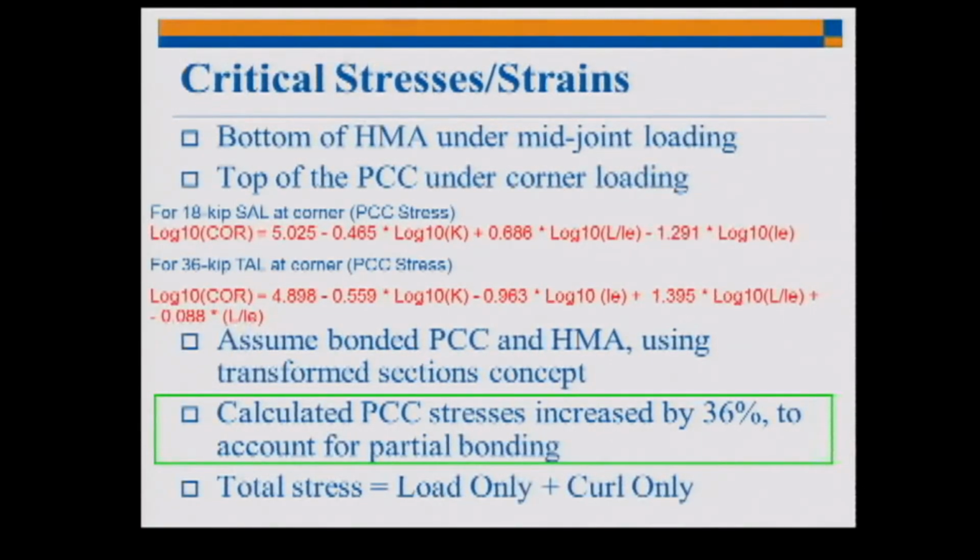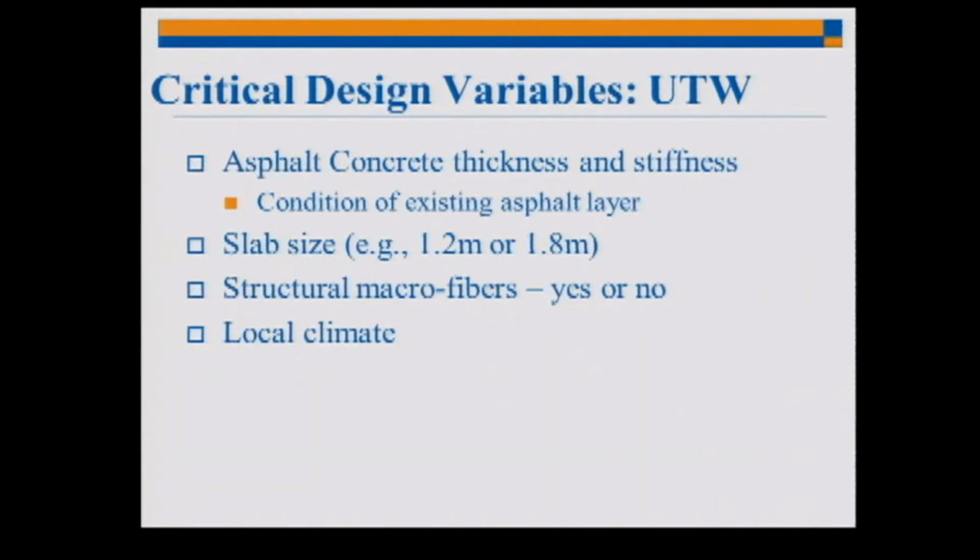Well, anyway, past researchers have developed stress equations to calculate the stresses in the concrete for various asphalt thicknesses and various slab sizes, and these equations are well known. And so when you run the actual design program, this is a mechanistic-based design program, and all these calculations are included. When you're thinking about the structural design, these are the main factors you need to get a handle on.